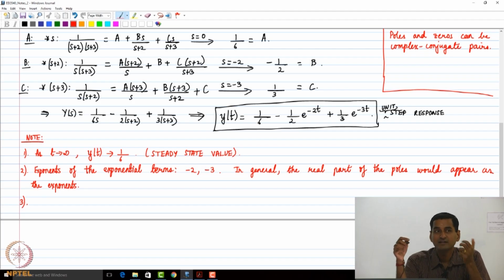Do you think the magnitude of y of t is bounded here? Do you think it's stable in that sense? Well, the answer is yes, but please note that it should be bounded for all possible bounded inputs. We are testing only one case, and it so happens that it is BIBO stable. That's a generalization I want to make here, but we'll prove it more carefully later when we look at stability.